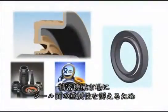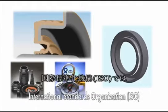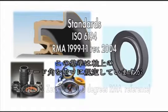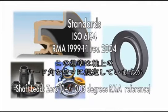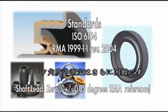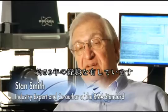To drive high-integrity sealing surfaces into the precision machining market, the Rubber Manufacturers Association of America, RMA, and International Standards Organization, ISO, have established standards for dynamic sealing systems. Both standards specify 0-degree lead on the shafts, which has been difficult to machine precisely and even more difficult to accurately measure. I've been in this industry, the oil seal industry, for approximately 50 years.